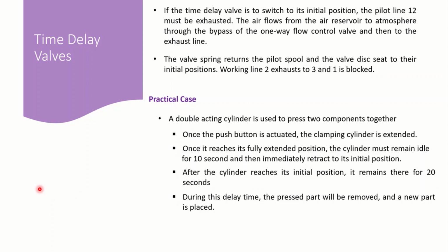And if you see a problem like this, you need to put a certain amount of delay, right? And therefore you need to have a time delay valve. After the cylinder reaches its initial position, it remains there for 20 seconds. It means we have another time delay valve. The system operates based on using two time delay valves in two different conditions.